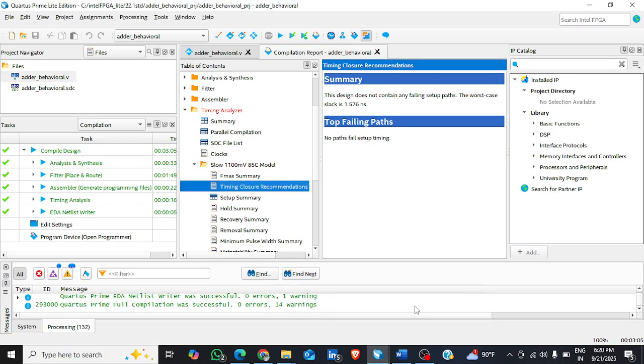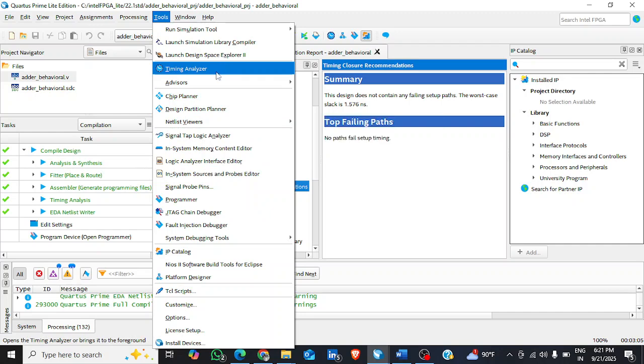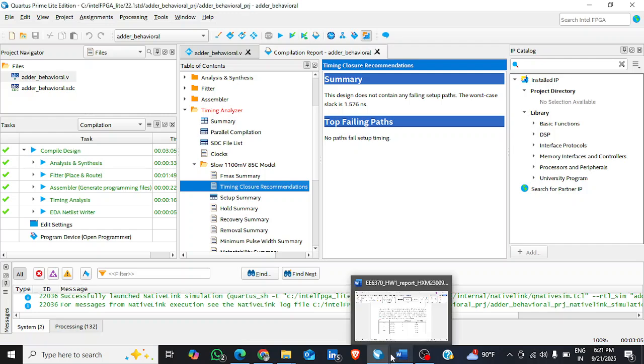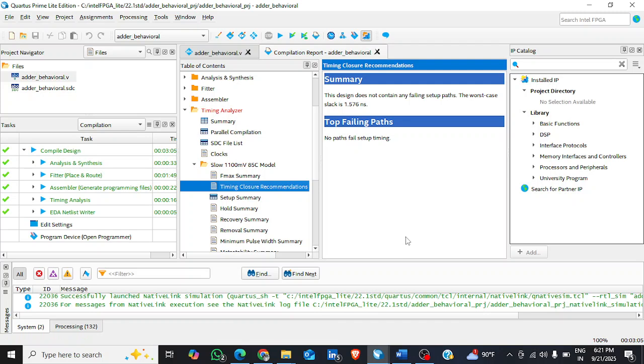We can also run this simulation. And this is the behavioral model, and then we'll also be looking at the structural model. In the structural model, it's built using the 1-bit full adder as a component, which is then chained together in this main file using a generate loop to create a ripple carry adder. So that's the structural model.